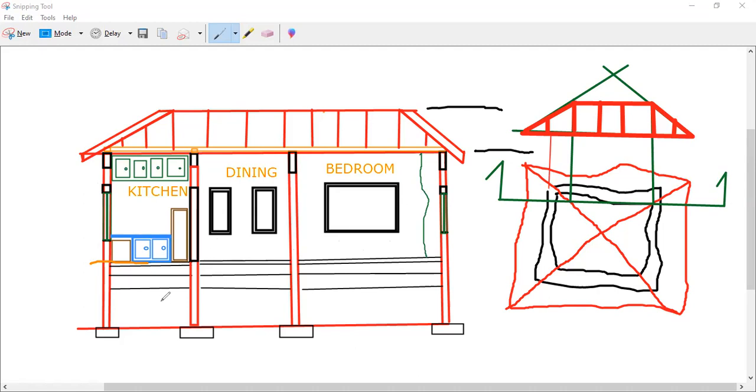Also, I think they gave us the detail for the different layers. So this would be our screed. This typically is our slab. Screed, slab, hardcore, and below that we find the earth. Of course, I've gone through these before. So this is basically a framework. Here would have been our wall and our footing detail. Up here is our ring beam and our wall plate.